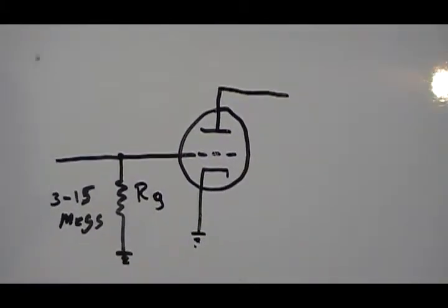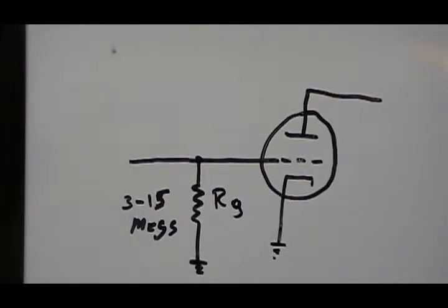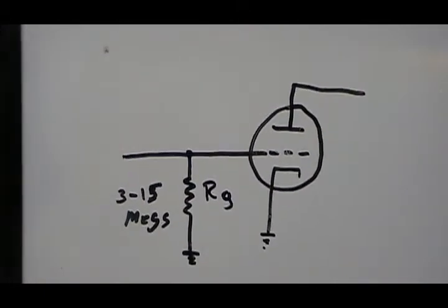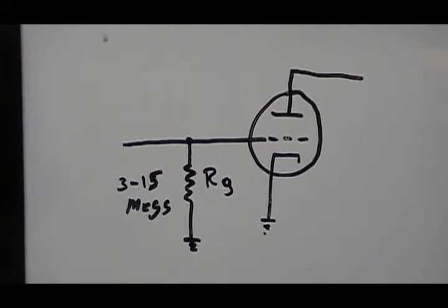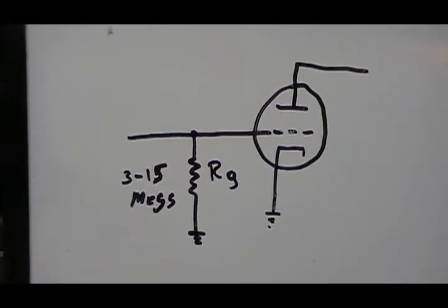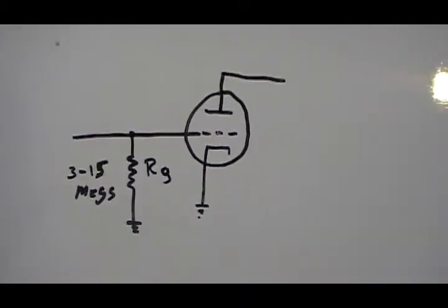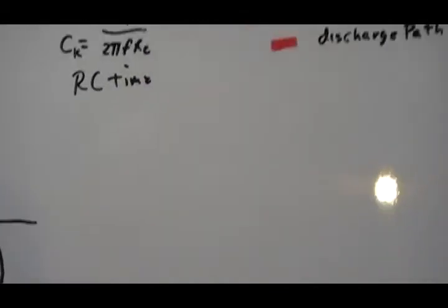contact bias will work. Now, contact bias is not a huge bias. It ranges between 1 and 1.5 volts max, but it works. Like I say, the 6SQ7 is one tube that uses it pretty much anytime you see it in any radio. So that's pretty much it on biasing methods.